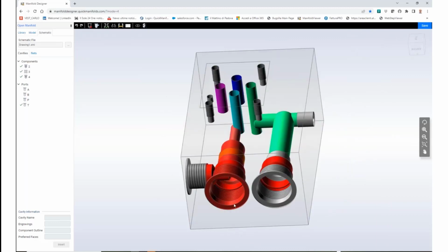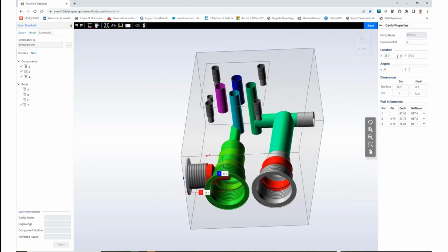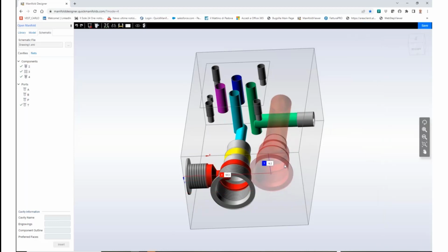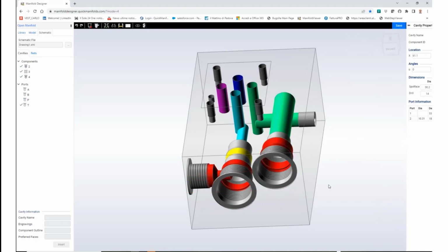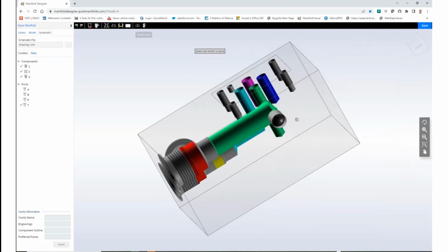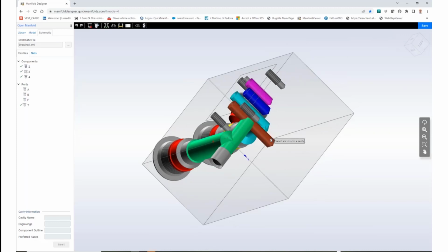There is not enough room here, so I can just move my cavity. And you can use directly this dialog in order to move the cavity. And again, maybe in this case, I will slightly offset my cavity, and I will slightly offset the plug, and I can stretch the drill. We don't need to be very precise.